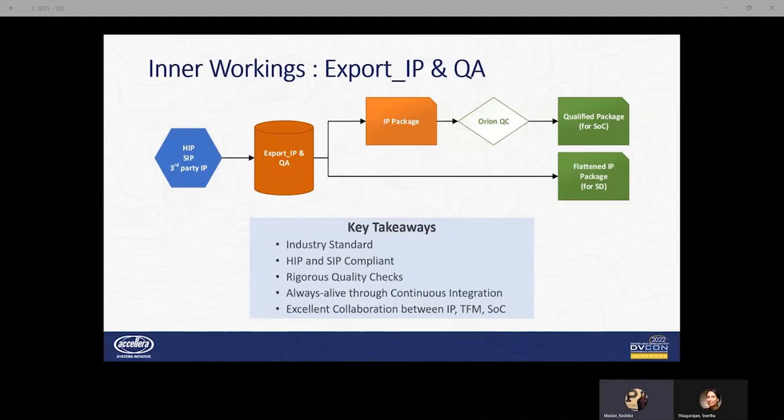This scalable QA setup allows IPs to effortlessly enable or disable any test based on IP readiness and their commitment to SoC. As of now, Spyglass design compilation on the RTL file list ensures basic synthesizability of the IP, and a multi-vendor standalone simulation on the RTL and val file list combined ensures strong LRM compliance is supported.